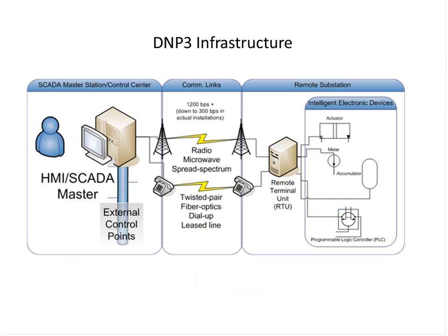Now let me get into DNP. DNP has been around for the better part of 25 years or more. It has supported transmission and distribution protocols in North America, the transactions that you need to field equipment during this period of time. And it has worked very effectively. And the reason why it works so effectively is because it puts very minimum requirements on bandwidth and processing capability on the devices.